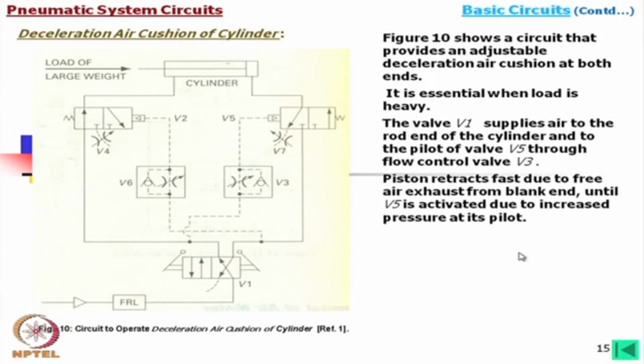The piston retracts fast due to free air exhaust from this end until V5 is activated due to increased pressure at its pilot.